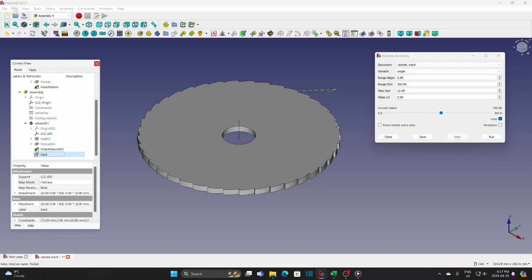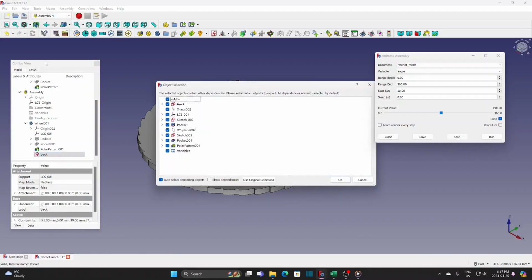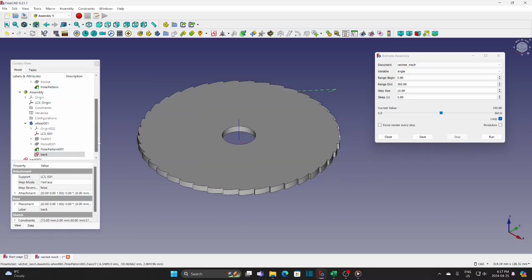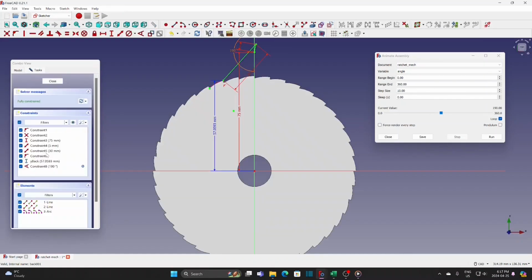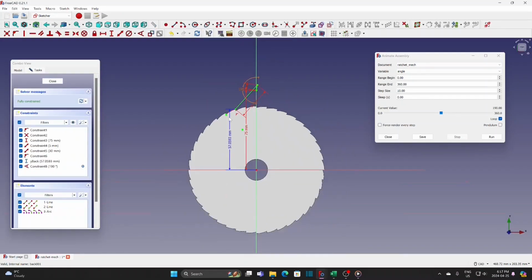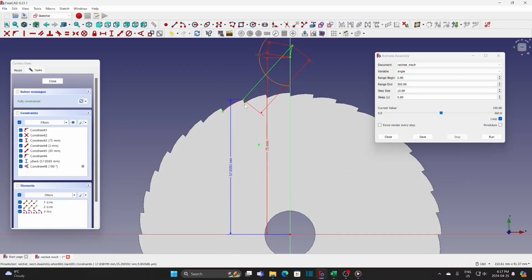Select the sketch and make a duplicate. We name it as fourth. Move it to the body below. Remove the constraint so it doesn't snap to the arch.